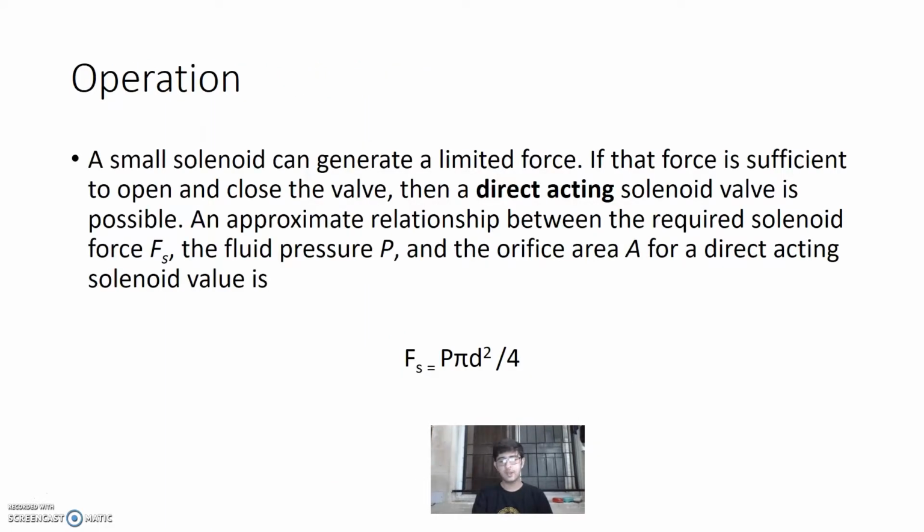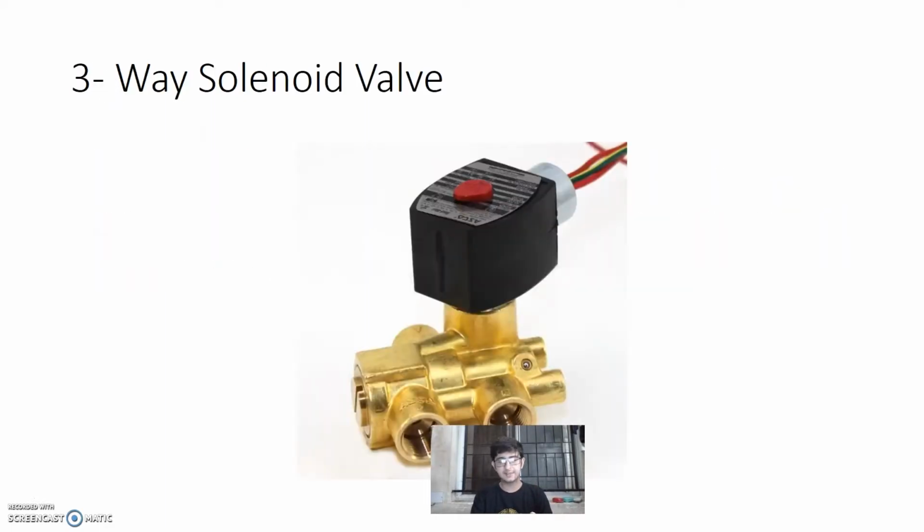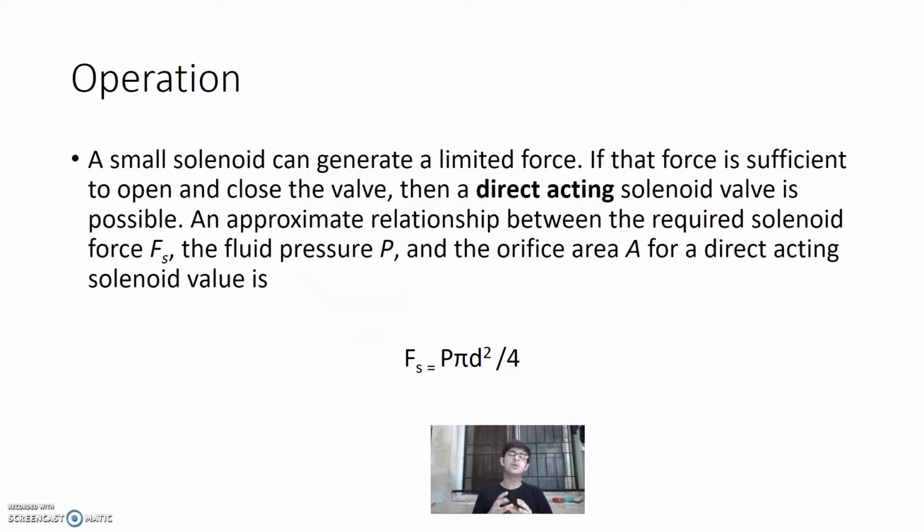Okay, before going to direct acting and indirect acting, let us discuss what the operation of a solenoid valve is. Basically you need some force to open the valve or close the valve, right? Even if you are doing it by hand, you need some amount of force to open or close it. Now we all know that if the fluid is flowing at very high pressure, you need more load to open the tap, right? And if the pressure of the fluid is somewhat less, the force which we apply on the tap would be less. So we all know force equals pressure into area.